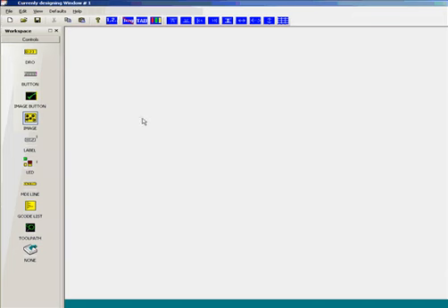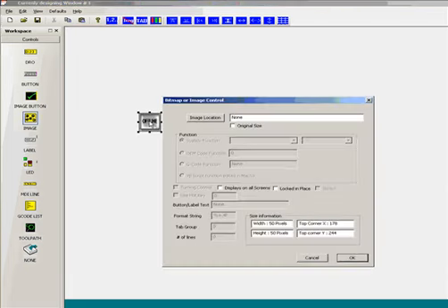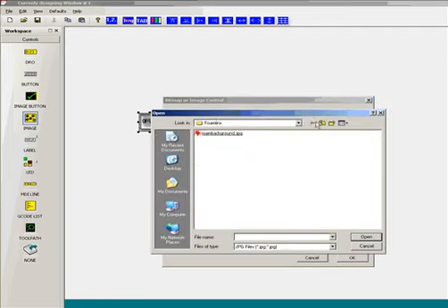First thing we're going to do is insert an image. I've prepared one earlier, and we'll have a look at what that is. So we'll just click on the image, click on the screen, you'll see this box appear, double click on that, image location. Now you'll find that all bitmaps have to be placed within the Mach3 folder in the bitmap folder, and then you can just create your own folder for the screens that you're designing.